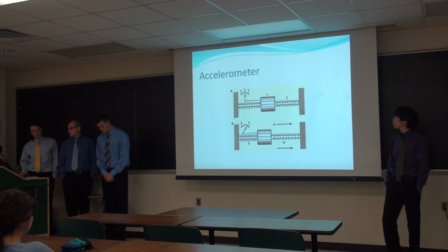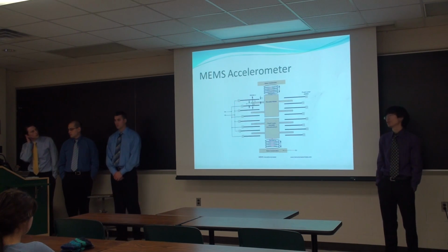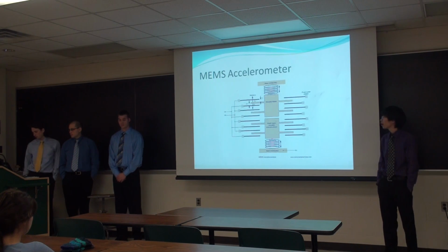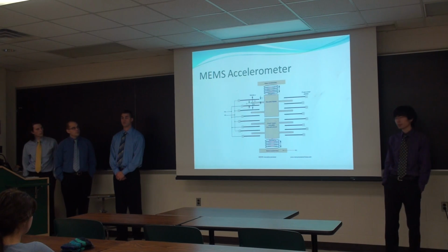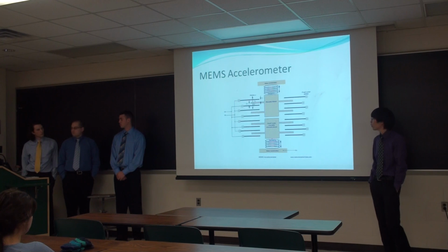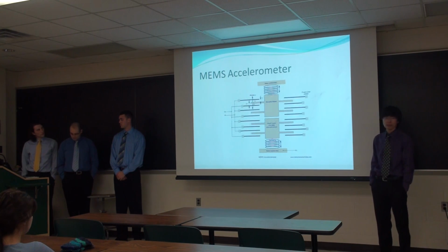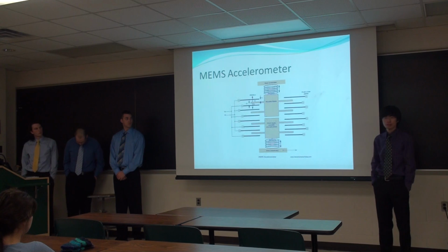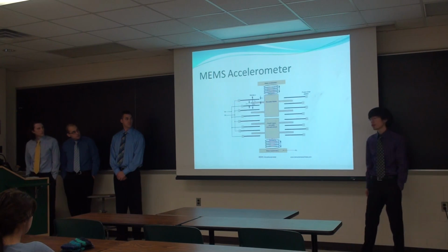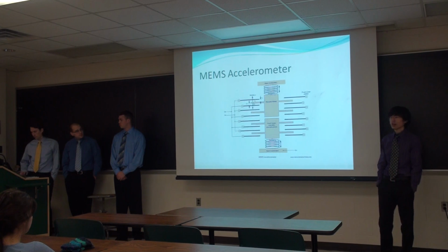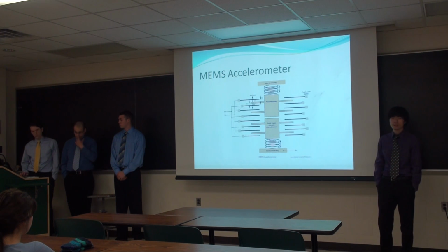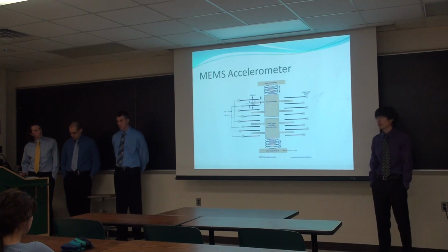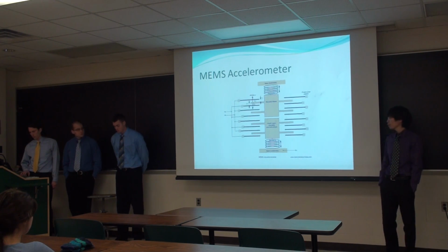And next slide, please. The accelerometer that we are going to use is a MEMS device, which is a micro electrical mechanical system. After a certain kind of chemical reaction on the silicon chip, it will create different fingers, like capacitor fingers. Those are the fixed plates, and after we apply voltage on that, we'll have capacitance, and we'll have moving plates too, acting in the middle of the capacitor plates, and that will change the capacitance, and then the voltage output acts as the G value.